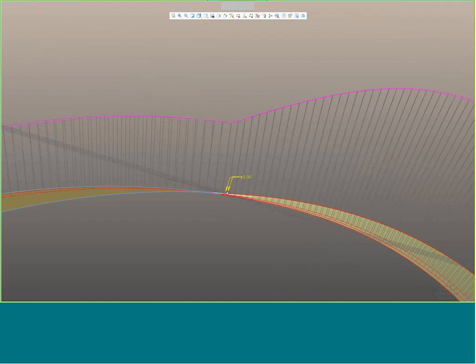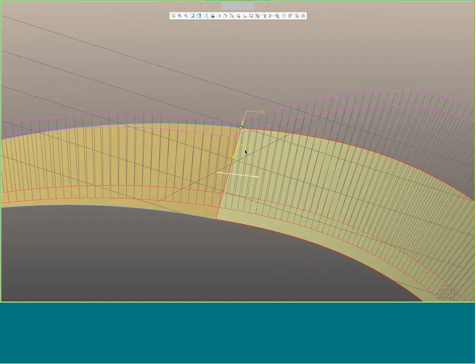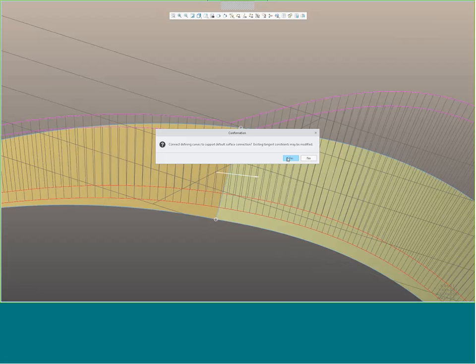So that means that we've now got one level higher polynomial, if you like, to define the curvature of this surface, but it's still not perfect. It's really good, but I think it's not what some, I use the word conservatively, Philistines in the industry tend to think of as A-class. Some people tend to think that you have to have G3. So now we've given it to you. If I go and pick on G3, do you want to update the curves?